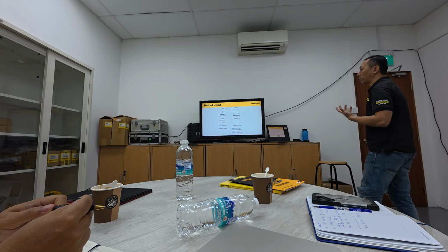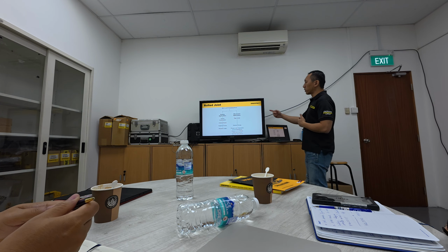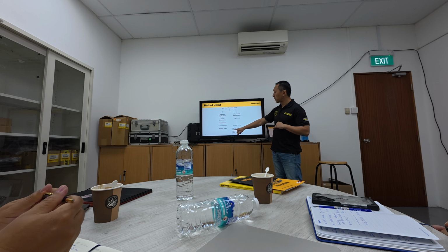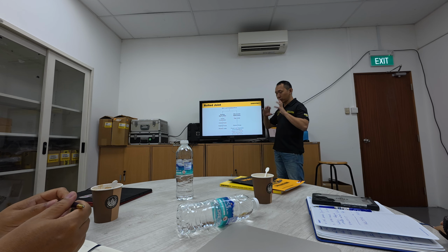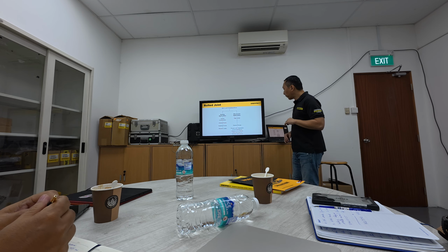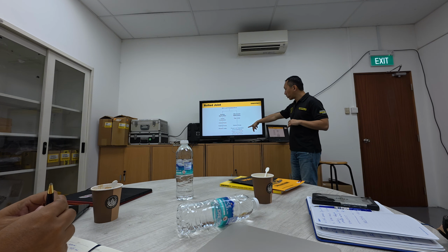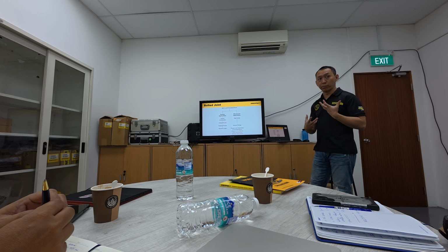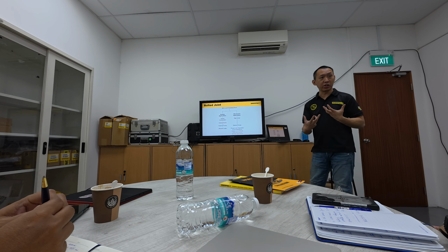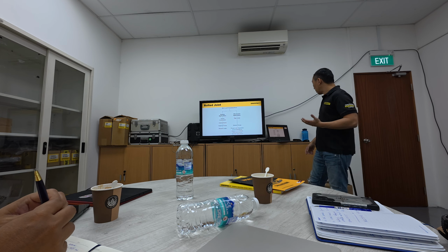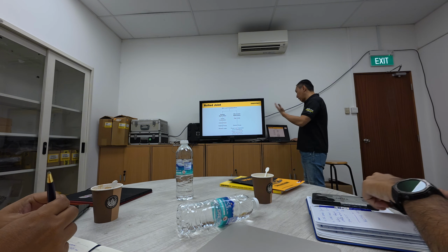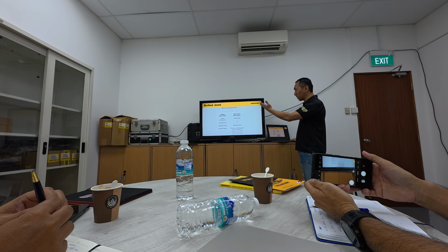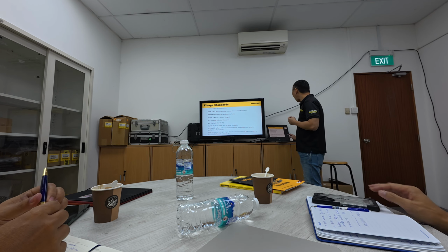Okay, the bolt clamping force, there's a difference. For sealing application, gasket compression, there will be internal forces and external forces. This is to prevent leaks. Mechanical is rigid, it's hard to join. So the main external force is to prevent the joint separation or bolt leakage, fatigue, or nut shaking loose from the bolt in vibration application. Okay. So clamp force, that's actually the difference between sealing and mechanical.